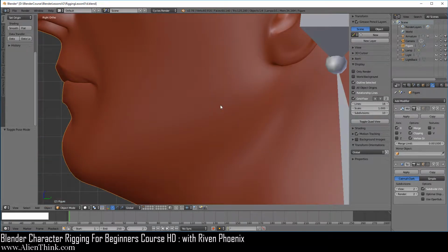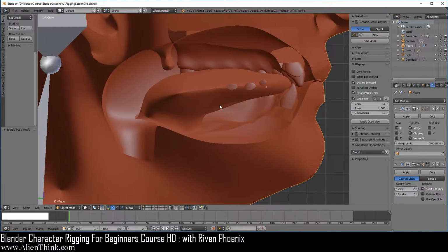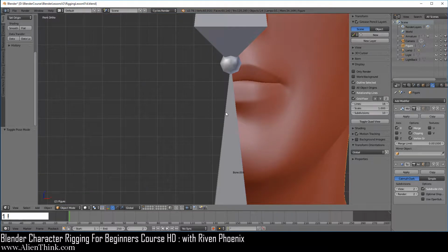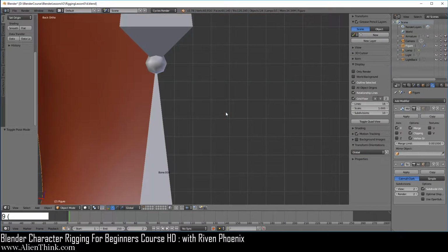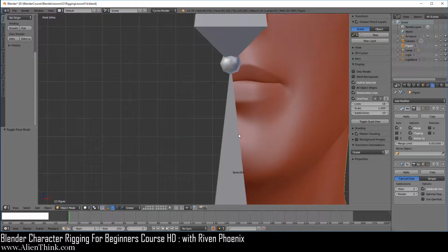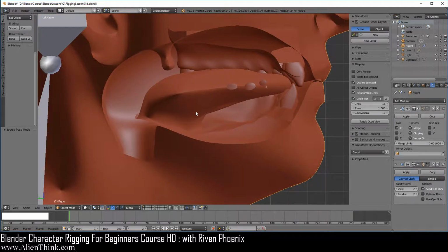If you press the 3 key, it's the right view, and you can simply press the 9 key, it'll go to the opposite view. It's the same thing for all the views. 1 is front, Control 1 is back, right? 1 is front and 9 is back. So anyways, we're going to press 3 and 9 to quickly switch the views.